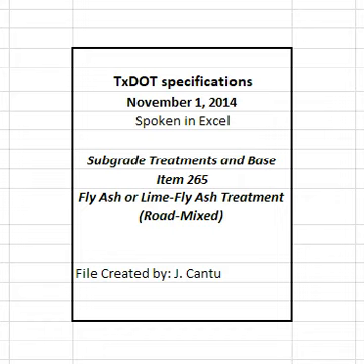4.3.1.1 Dry placement. Before applying lime, bring the prepared roadway to approximately 2 percentage points above optimum moisture content. When necessary, sprinkle in accordance with Item 204, Sprinkling. Distribute the required quantity of hydrated lime or pebble-grade quicklime with approved equipment. Only hydrated lime may be distributed by bag. Do not use a motor grader to spread hydrated lime.